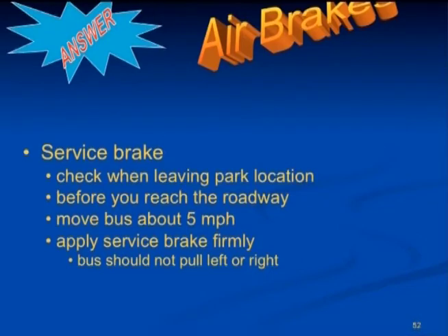For the service brake check, check before leaving the park location. Move your bus to about 5 miles an hour. Apply the service brake firmly. The bus should not pull left or right.